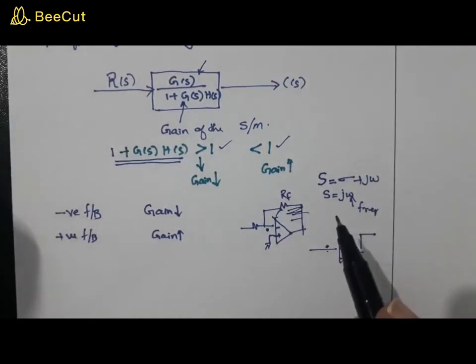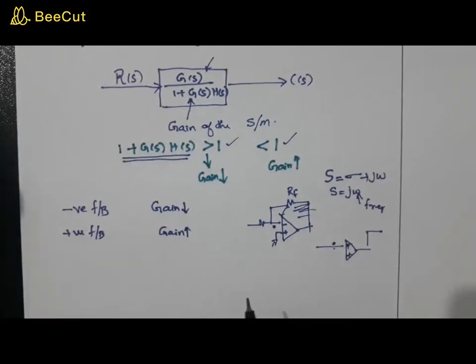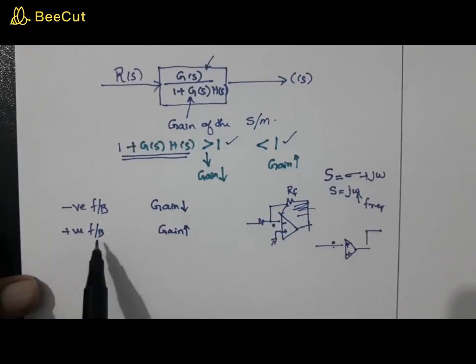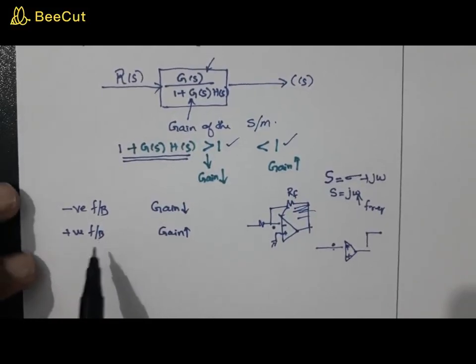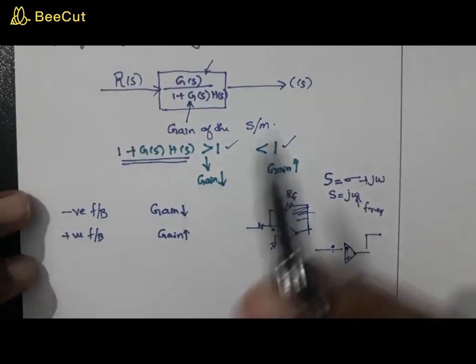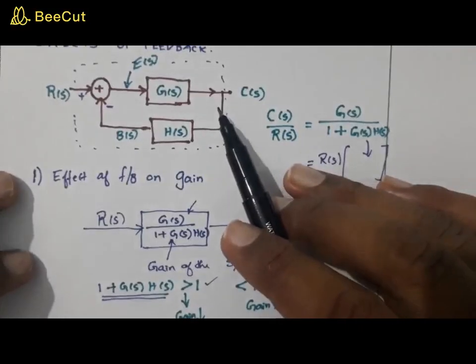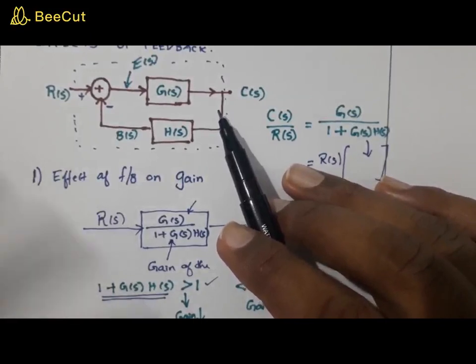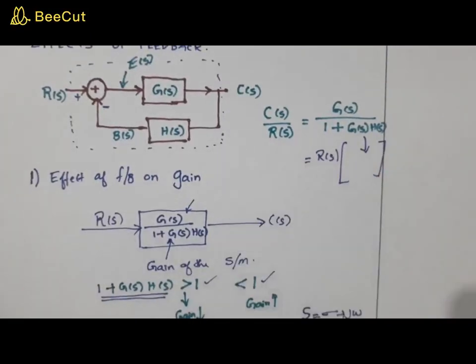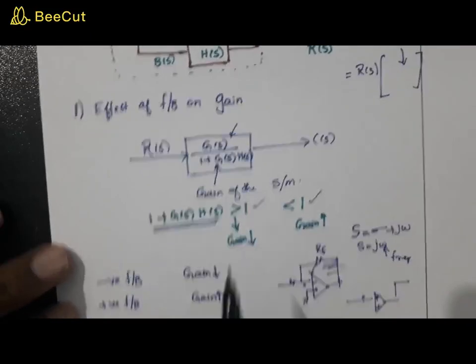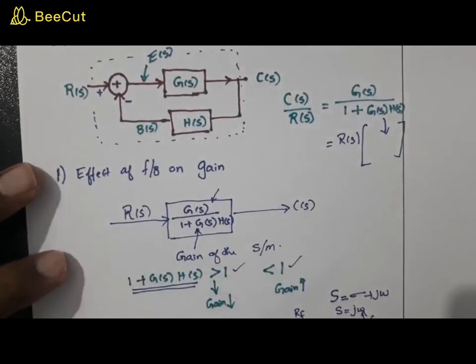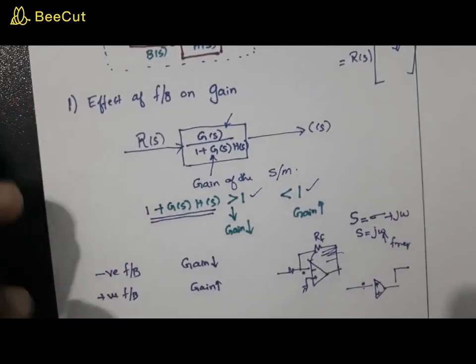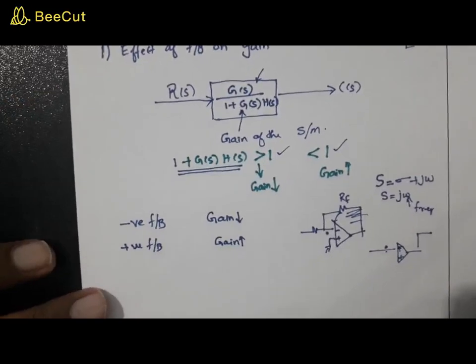Okay. Now, similarly, positive feedback also has its own advantage. When it comes to generation of signals, we usually employ positive feedback, while that is not good from a control system point of view, because that's the problem with the closed loop system. It is the positive feedback which actually makes the system oscillate, and which is not desirable as far as a control system is concerned.